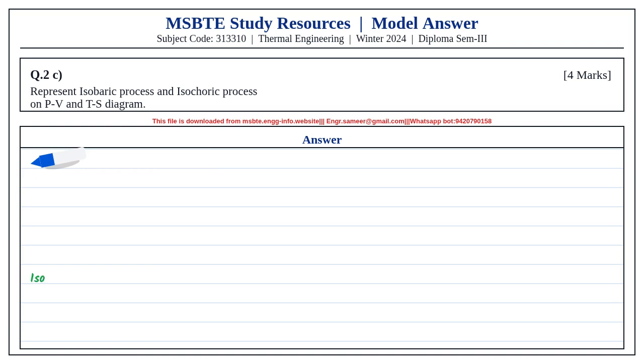Question 4c. Differentiate two-stroke and four-stroke IC engine. The table gives the main differences between two-stroke and four-stroke IC engines. In two-stroke engine, the cycle is completed in 2 strokes of piston, while in four-stroke engine it is completed in 4 strokes. Two-stroke engine gives 1 power stroke in every revolution, while four-stroke engine gives 1 power stroke in 2 revolutions.